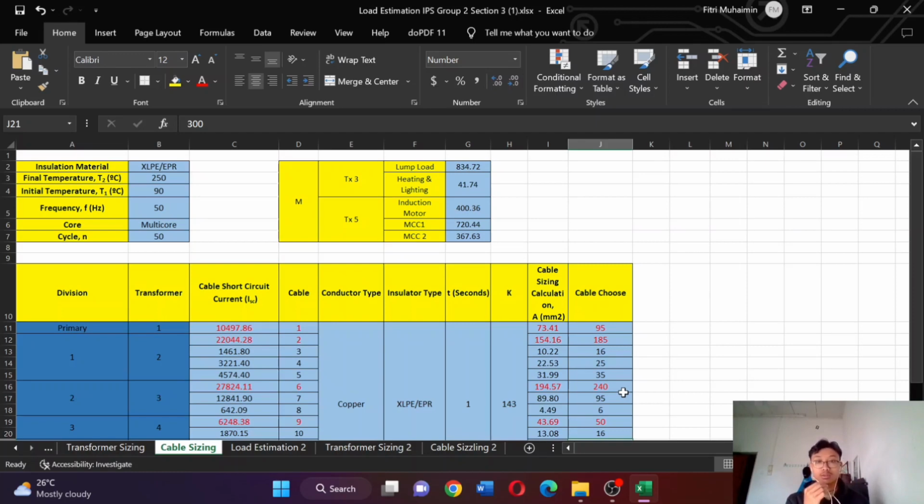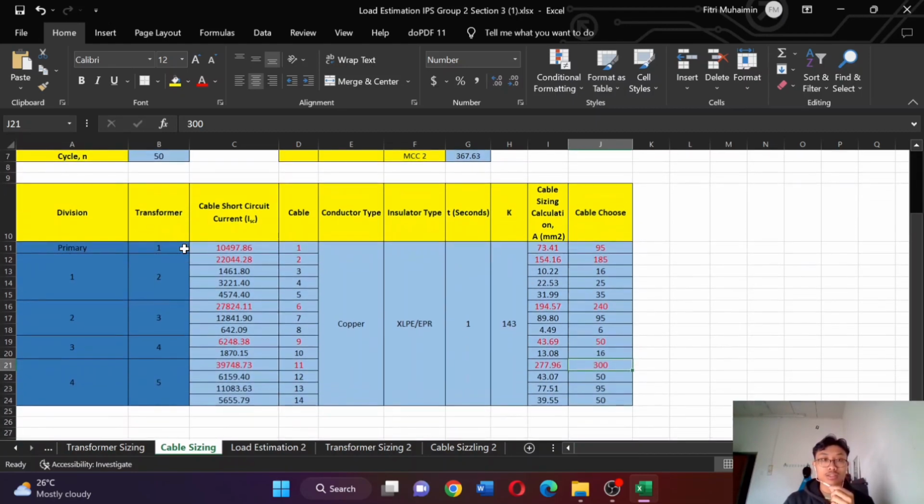Assalamualaikum warahmatullahi taala wabarakatuh. I'm Muhammad Alif Nazmi bin Asmadi, and I will explain about the cable sizing for transformer and motor. So the type of cable that we choose is copper, insulation XLPE EPR. The final temperature is 250 and the initial is 90. The core is multi-core. And next we should go to the cable sizing.